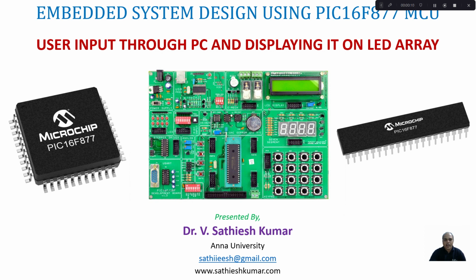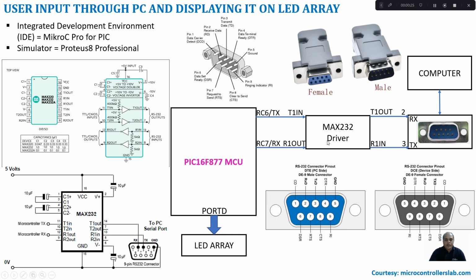In this tutorial, I will be describing how to provide a user input from a PC and activate the corresponding LED array depending upon the input. So in this application, we are going to activate the LED array depending upon the user input from the computer. The computer will be connected through a MAX232 driver to the microcontroller.